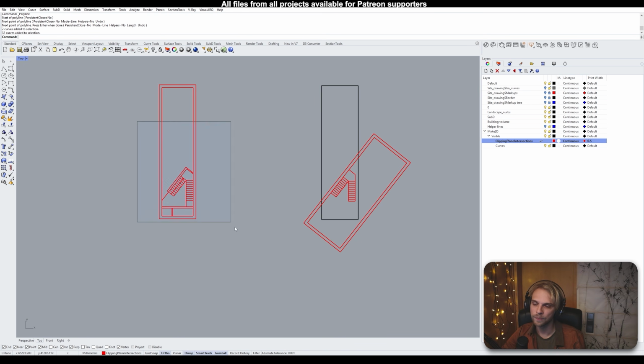So now, also, as I was modeling the staircase, since we have a 4-meter height in the first floor, the staircase didn't fit properly, so I had to give a little bit more breathing room, especially along this edge right here of the building. So as you probably saw in the footage, I have added 50 centimeters, 500 millimeters to the thickness of the building.